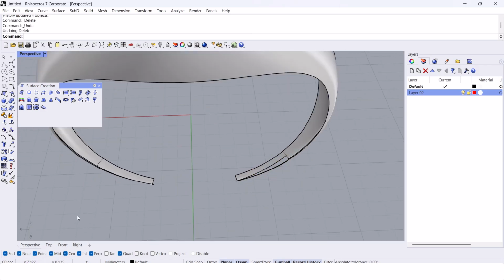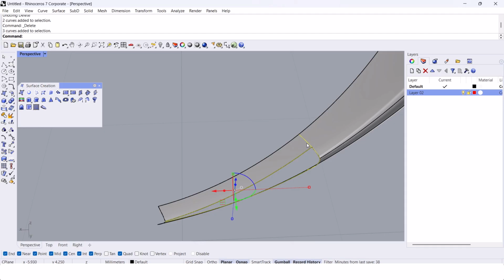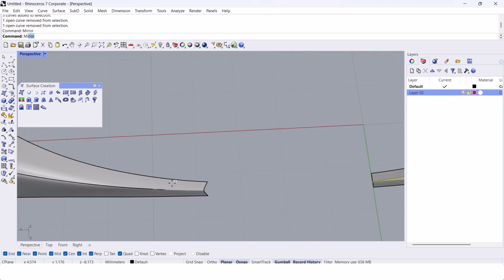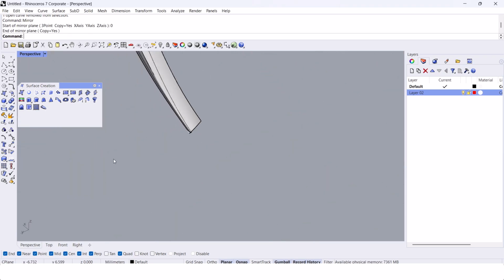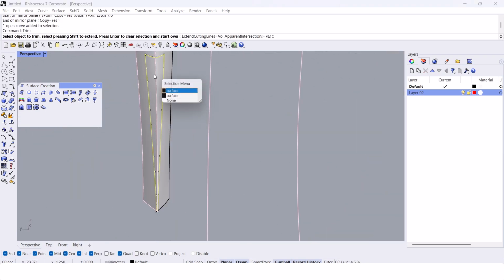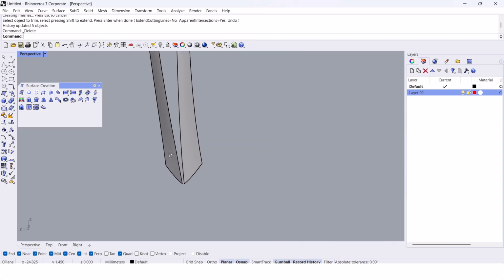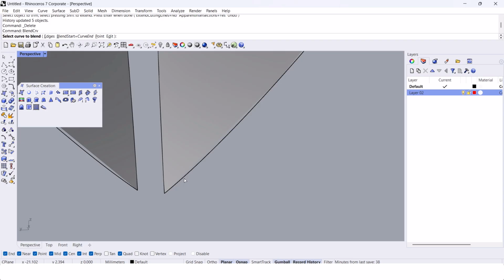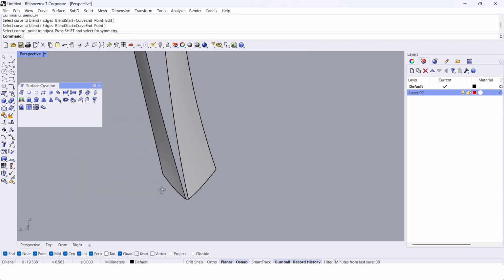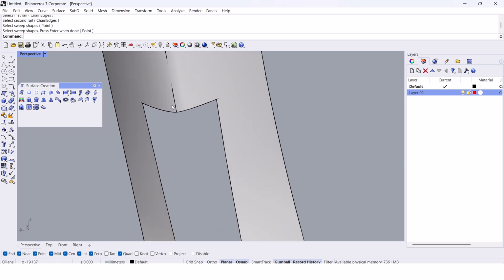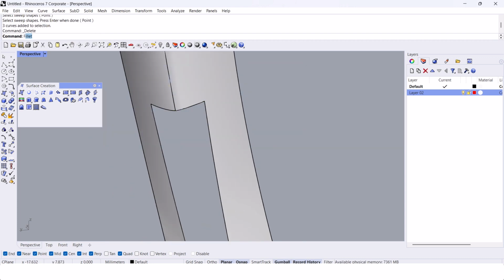Also, you can use the same curve for the other side of the ring if your ring is symmetrical. If your ring is not symmetrical, you have to do it again. Then I'm going to use the blend curve. I have a cross section here, with 2. So I need to do the duplicate edge and make a cross section at the top as well. Join.